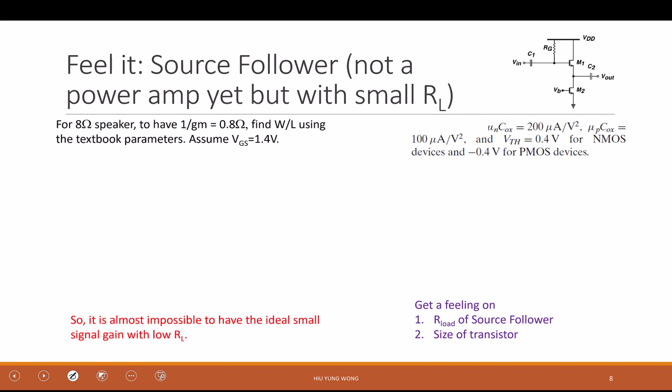If you forgot the equation in the interview, at least you should tell approximately what the gain of a source follower should be. What is the meaning of a follower? Just give me an approximation. No need to think about the equation, right? Remember what we said about follower? Like the younger brother follows the older brother? Yeah, the input is the same as the output, except it is shifted, right?